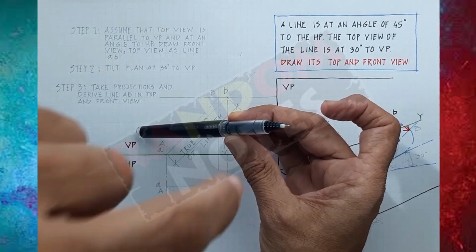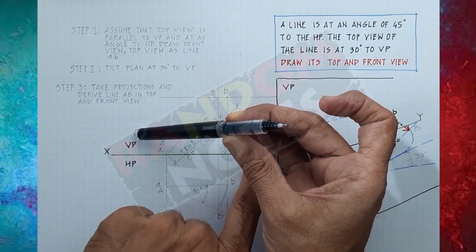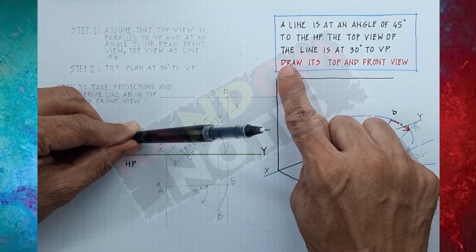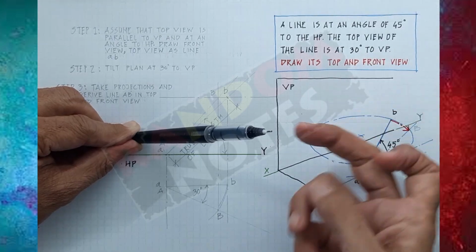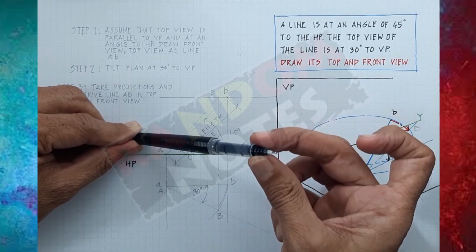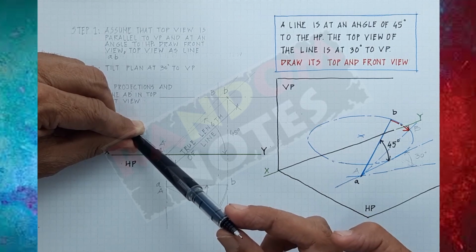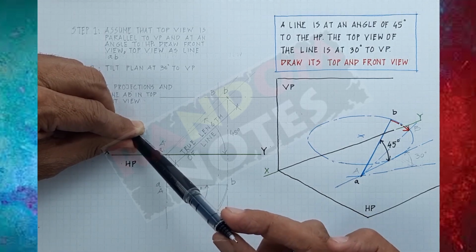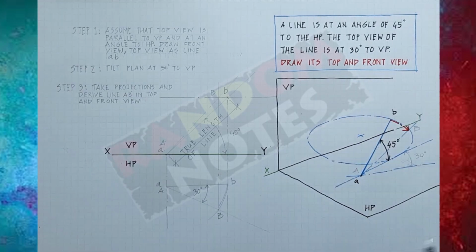When I see from top, I will see the projection of this point and this point down to the horizontal plane. The next condition is the top view of the line is at 30 degree to the vertical plane, which means this is at 30 degree to the vertical plane. This is the condition which we have to use to draw its top and the front view. Let us see out here.